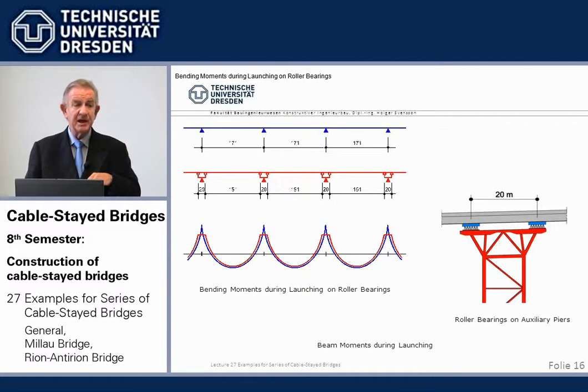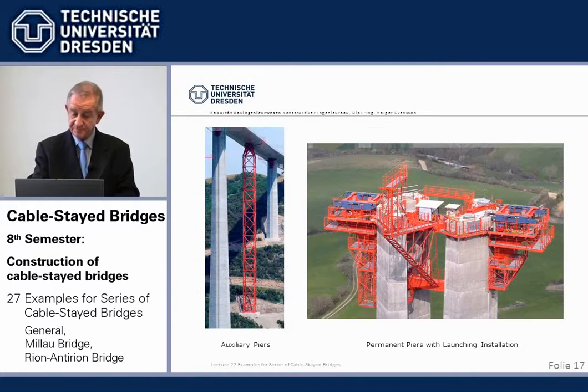And when we have in the final stage a 342 meter span with a 4.2 meter deep girder, 1 in 80, that's not too extraordinary for a cable-stayed bridge, quite usual. However, if we think of the cantilevers during launching, we come to 171 minus 20, 151. So we come then to a slenderness of 1 in 35 for the cantilevers. And that's quite unique, how to overcome that.